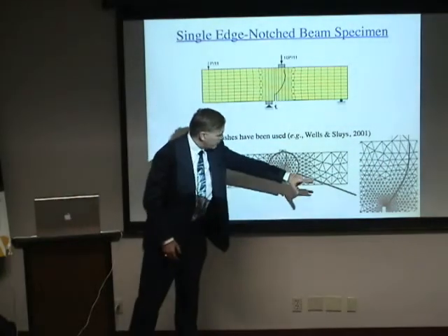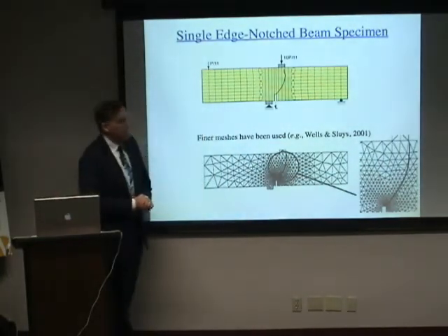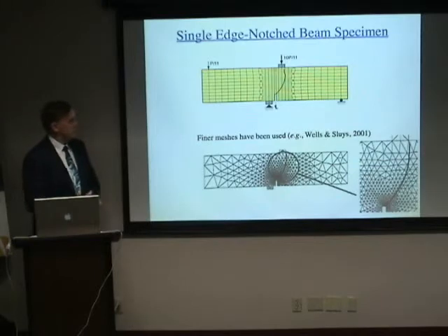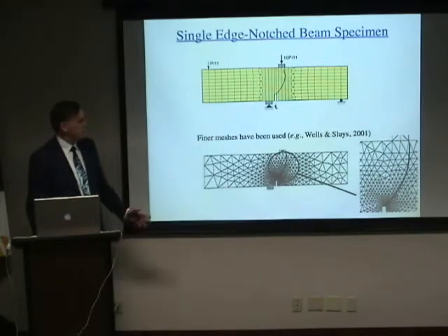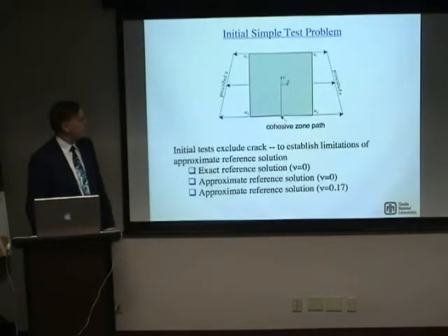So this is with Heaviside enrichment, and you can see that they're using relatively small elements, which, in some sense you would expect because you need to pick up the gradients around the crack with the polynomials as opposed to the enrichment. There are other examples in the literature, for example, on people solving this with non-local formulations, and likewise they had to use relatively small meshes.